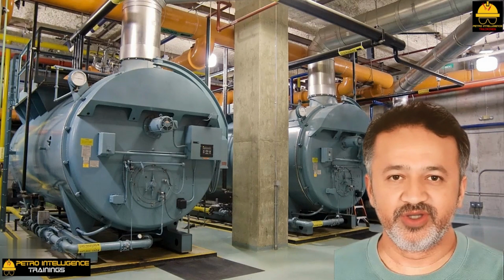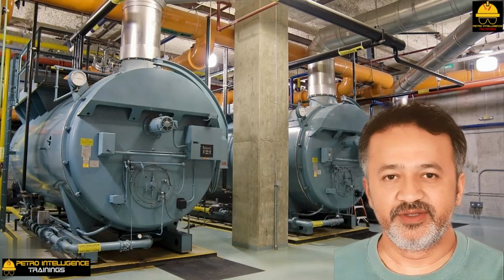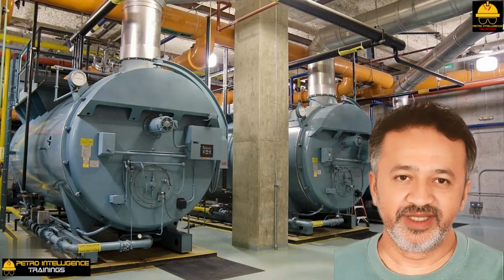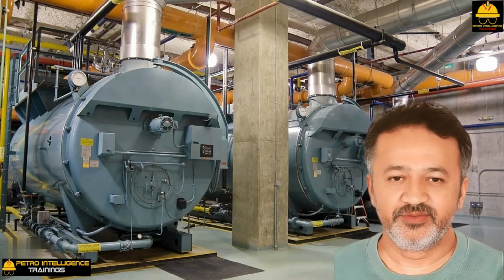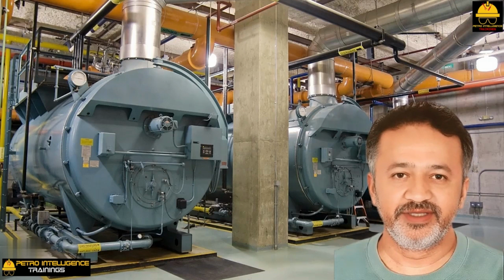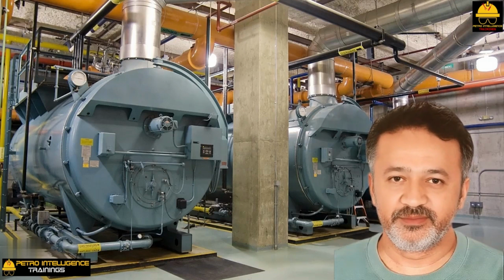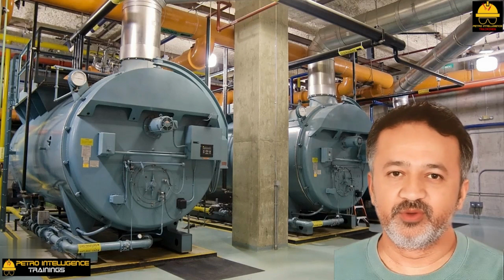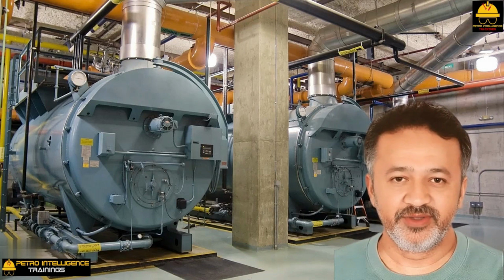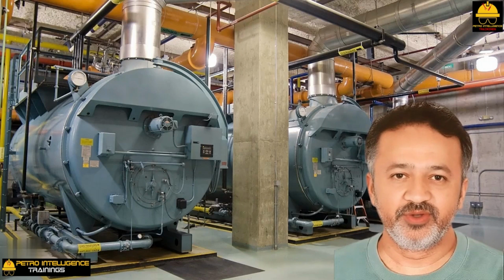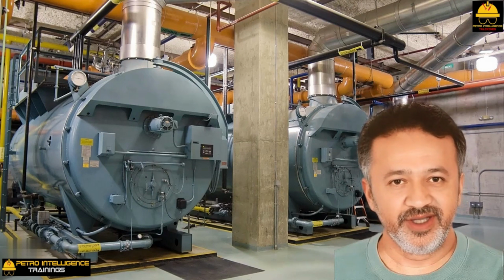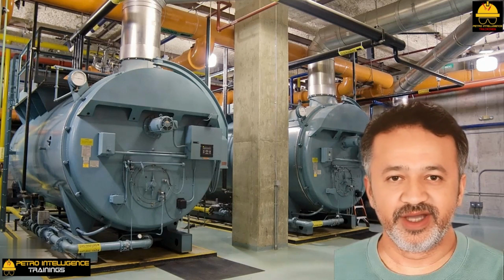With the radiant section just as hot with or without the air preheat, I would think that steam production would remain constant, so why would it drop off? The answer is that air preheat requires less fuel gas firing, and thus less flue gas and hence less heat pickup in the convective section. While the radiant section heat transfer rate will remain constant, the heat transfer rate in the convective section will drop in proportion to the reduced fuel gas fired. A 200 degrees Celsius air preheat, 20 to 220 degrees Celsius, will save 10% of the fuel and thus reduce the flue gas flow by the same 10%.